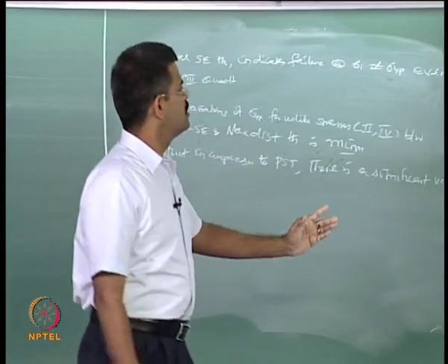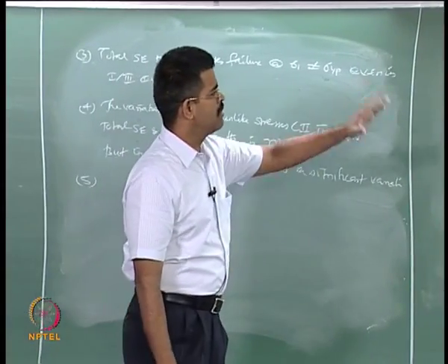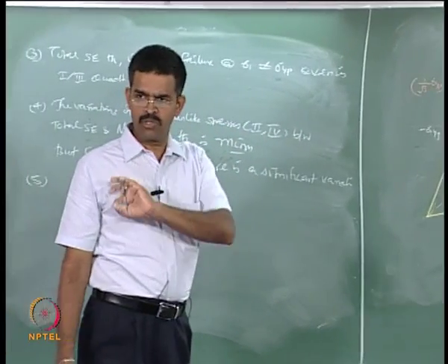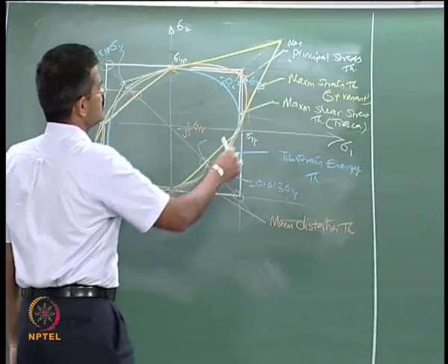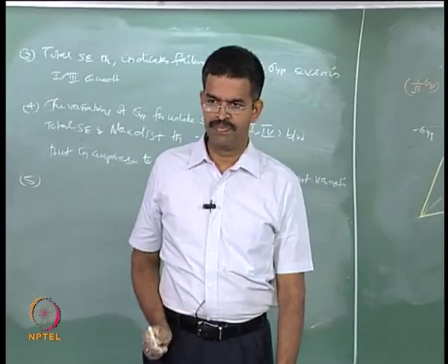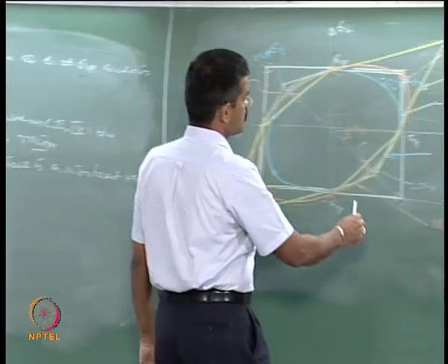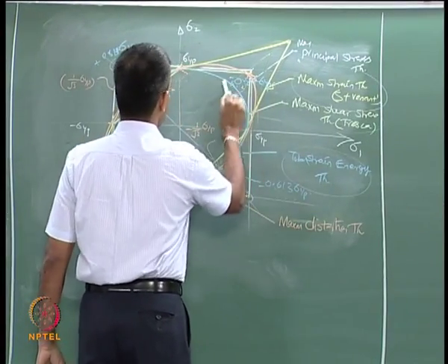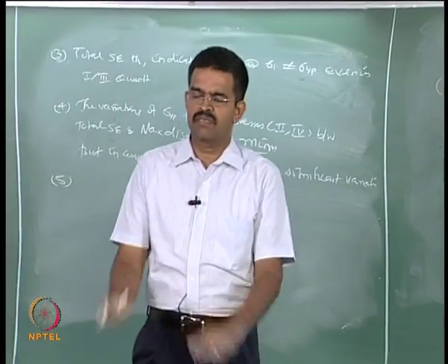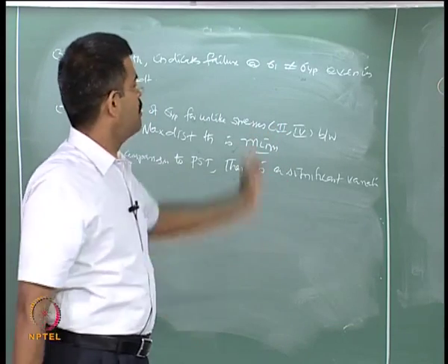Okay. Do we have any questions or any more important information or interpretation which I left out by comparing these theories? The most important and eye catching information which you must not miss out is the comment or the focus of Saint-Venant compared to principal stress, okay, and the focus of total strain energy theory in quadrants 1 and 3 compared to principal stress. These are the two important, predominantly or significantly seen variations in your comparison of failure theories.